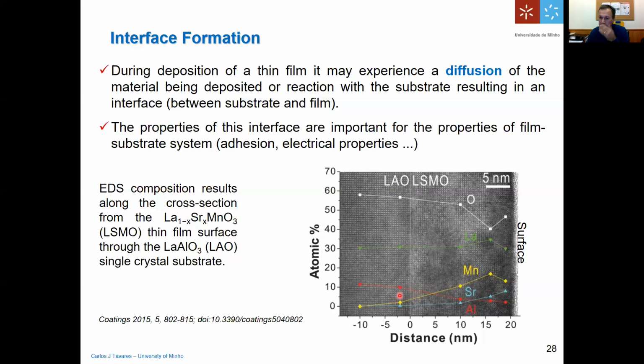Okay, and also the lanthanum content is not constant throughout the whole cross section from the substrate to the thin film. It varies a bit here. It is constant on the substrate. So there are some zones which are richer, because here we have more lanthanum, and maybe you have some stacking faults here which are richer in lanthanum, because this grain here is darker, and then it decreases.